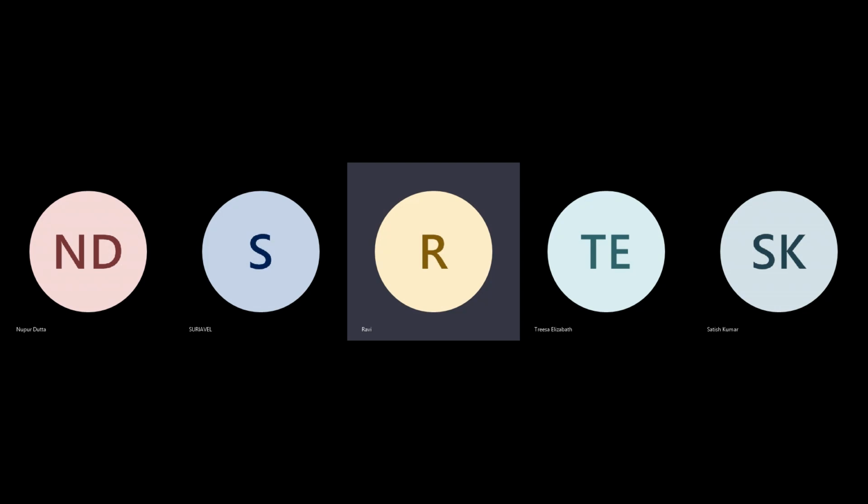Yes, DCT has two options. SPG means it will use your floor plan. Design Compiler Topographical without a floor plan will also work. The difference between DC and DCT is that DC will do just logic synthesis. DCT can do placement. So if you don't give a floor plan, it will do automated macro placement by default, and it will do placement and legalization. So these are things that you could have done.